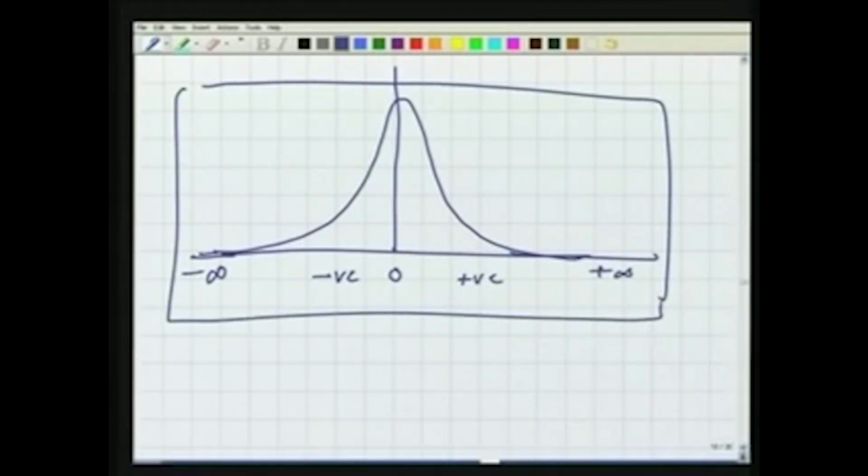So, what we saw today was about the errors in the observation, the errors in the measurement, and this is a very important concept. We should know about these errors, because in surveying you go to the field and measure something there, so you should know what kind of errors may creep in. These errors come because of nature, because of the instrument, because of you, the person. Second, we talked about the types of errors. There could be mistakes, and there could be systematic errors. We can eliminate those systematic errors provided we know the mathematical model or the physical law which they follow. We can also apply corrections for all the systematic errors.